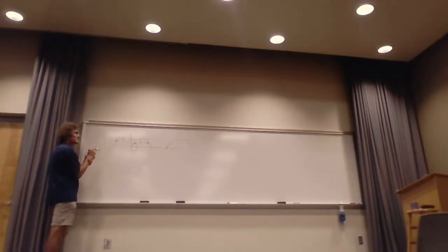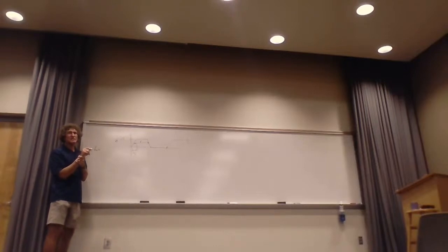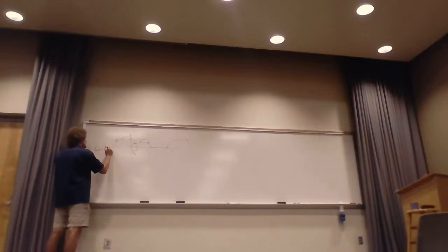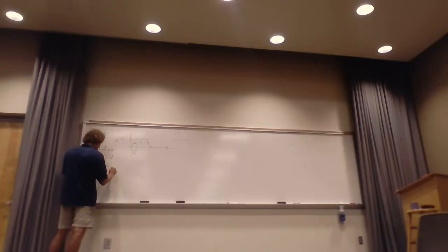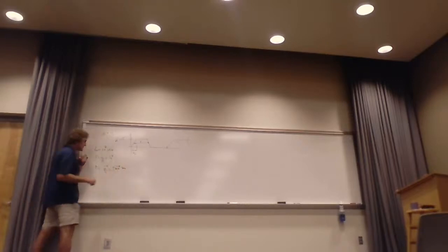The characteristic frequency, was that 100 megahertz or 10 megahertz? I forgot. 10 megahertz. So it's 10 to the 7th hertz. All right. That means T is 1 over F naught, or the period is 10 to the minus 7th. And that means because the duty cycle was equal to 1/2 or 50%, that tau was equal to 10 to the minus 7th over 2, or you could just put it simply 5 times 10 to the minus 8 seconds, however you want to do it. That's 50 nanoseconds, right?